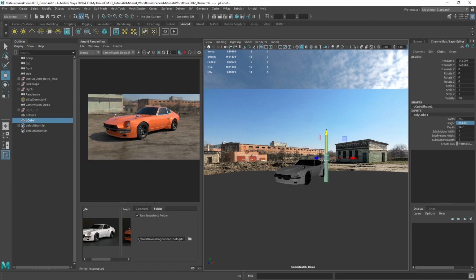And then I want the width. The standard width of a door is 36 inches, or 3 feet, or 91 centimeters. So I can type in now 91.44 centimeters, and there you go. You get the standard dimension of a door, height and width.